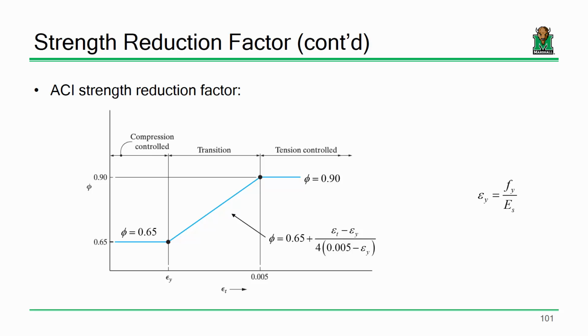See, phi is actually a lot more complicated in here than it is in steel design. In steel design, because you're primarily dealing with elements that are of a single material, it's just, oh, columns, phi is 0.9. Like, you just look it up. There's no determination. But in here, you actually have to determine that.